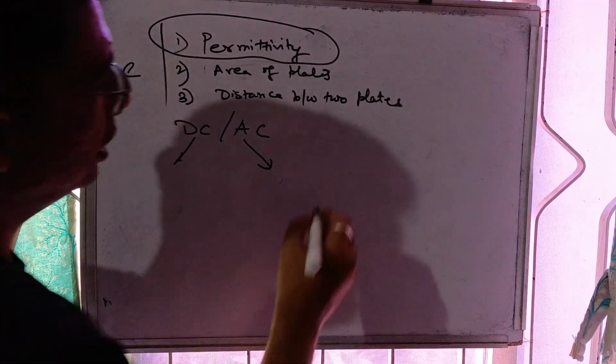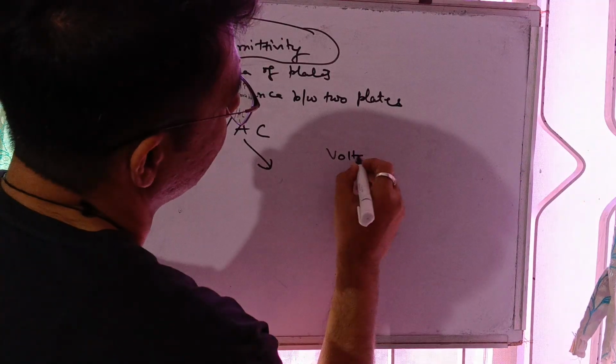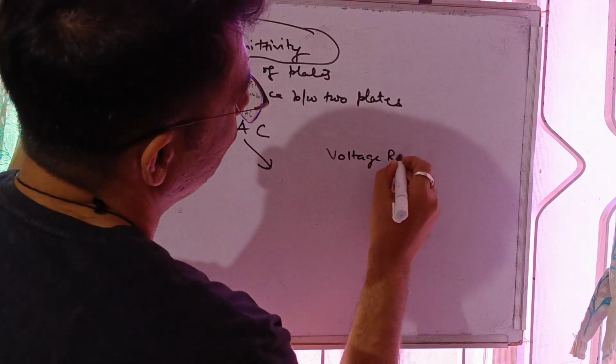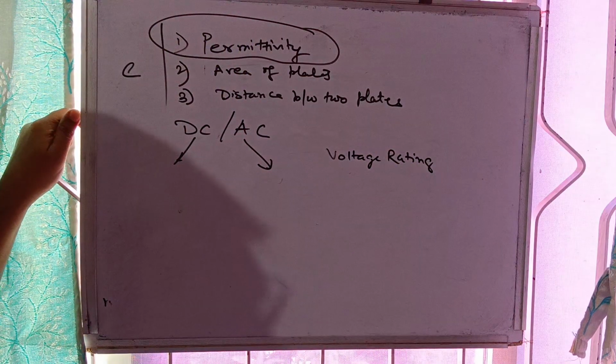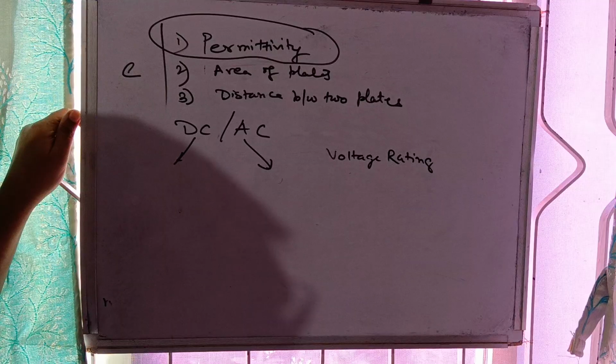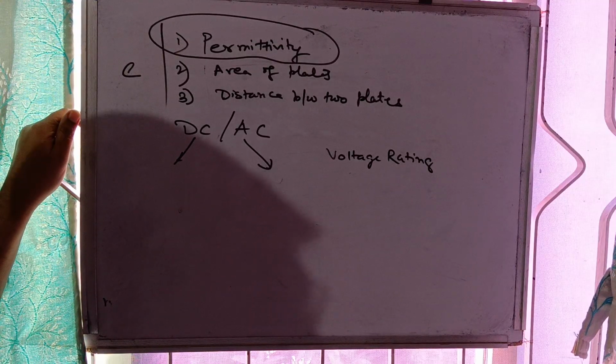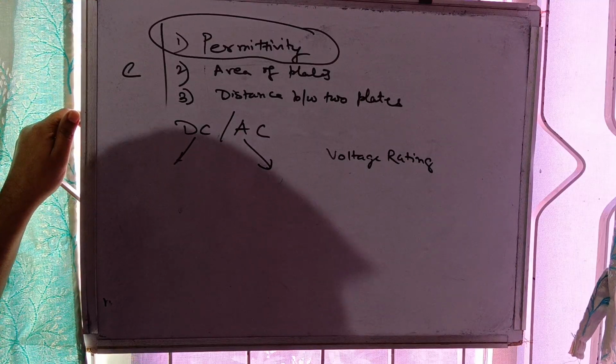But yes, most important is its voltage rating. So if your capacitor's voltage rating is less than the supplied voltage, then there is a possibility that it blasts. Not only a possibility, 100% it will blast. Clear? Thank you.